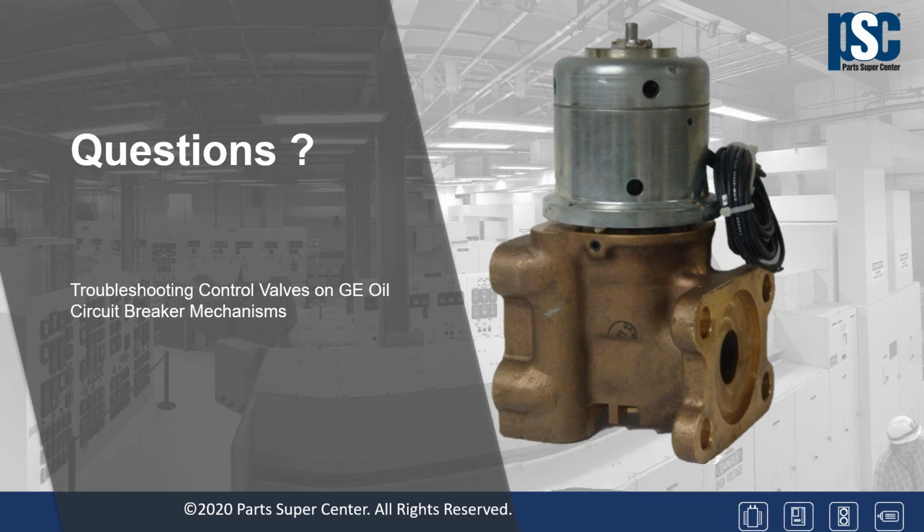We have a test stand that we can adjust with a variac, setting the control voltage to the minimum, maximum, and nominal control voltages. So we have a specification for what all of those are, and we go higher and lower than the minimums and maximums to make sure that the valve is going to operate at what the nameplate mins and maxes are. We also vary the pressures. So there's a nominal pressure that the control valve is supposed to operate on.